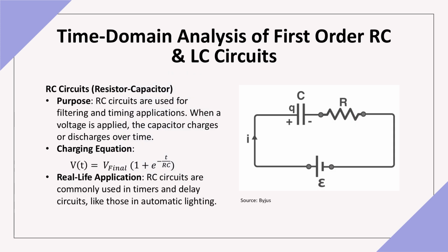Let's examine RC, resistor-capacitor, circuits, which are fundamental in timing and filtering applications. The charging equation for a capacitor is V(t) equals V final times (1 minus e to the power minus t divided by RC), where V final is the final voltage, t is time, and RC is the time constant. Looking at the diagram, we can understand the basic structure of an RC circuit.